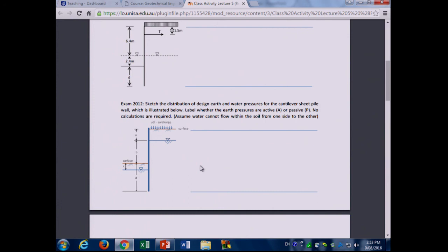When you draw the pressure diagram and multiply it by the 0.2 whatever, you make it smaller, is that right? But the slope stays the same. Just say for the top part above the water here, it'll be active. So say you draw it like that. Then if you multiply it by 0.26 or whatever, because it's active, do you have to draw that smaller? No, no, it would be even higher. It says multiply that factor with the unit weight of soil. So if we go up to this point, in the pressure diagram we go gamma z, and we get the pressure here.